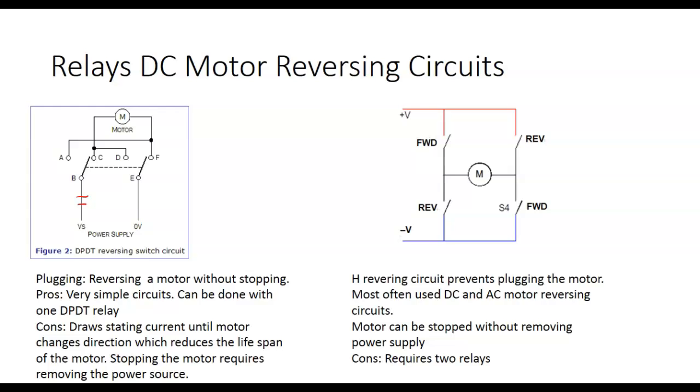On these electric motors, if you reverse them without letting them stop, it's going to pull that motor. And what's it called? Plugging. What's jogging? Yeah, this is when you run the motor in bursts. If you took robotics, that's what we call it, jogging.